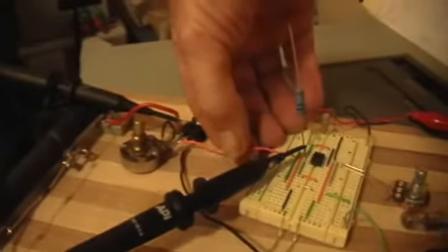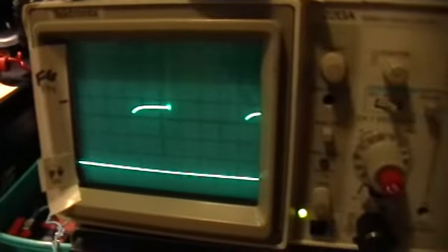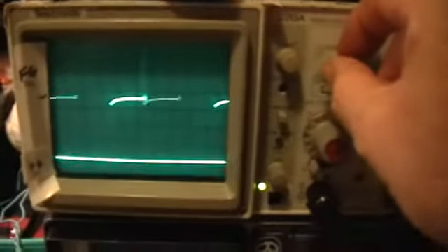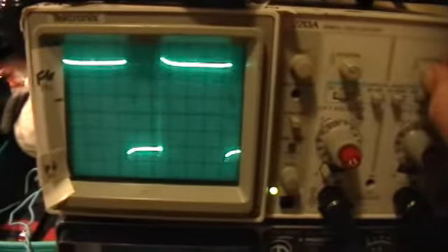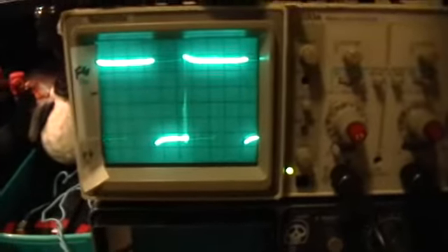Okay, now what I'm going to do is unplug the lead connecting the 555 timer to the rest of the circuit. Okay, so the MOSFET will die, and now all you see is, I'm going to just go ahead and turn that trace off. Now all you see is the timer trace, and I guess you can see that parasitic oscillation riding on it right there. Okay, and what I'm going to do now is magnify that.